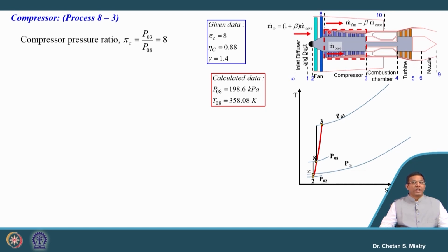Now, there are some ideas where, when people design the fan, they decide the distribution of the pressure. Say up to a certain percentage of the height of the blade we will have some pressure ratio, and on the upper side some other pressure ratio. That is a design strategy. Those who are interested can go through the course on aerodynamic design of axial flow compressors and fans, where we have discussed this in detail. So, you will get some other kind of feeling. Okay, so let us put this number.